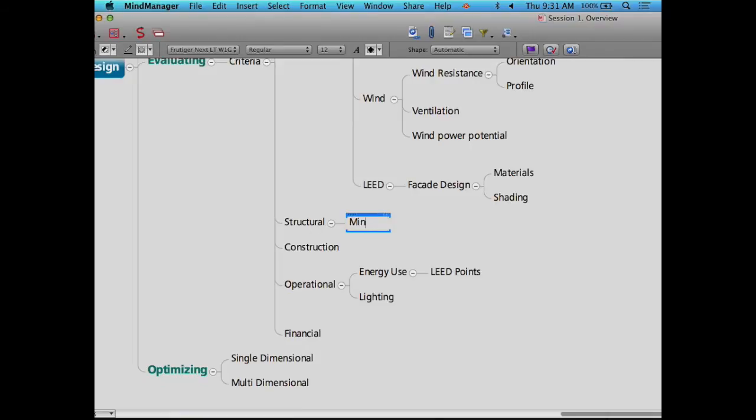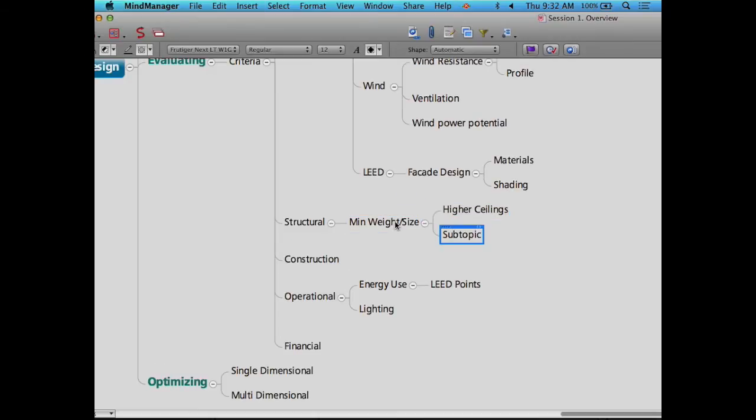Okay. And when you say size, is it size or is it weight? Or kind of both? Yeah, I guess it would be weight. Okay. Or it could be both, because you want to minimize the weight, but you also want thinner members, right? Mm-hmm. And why do we care about that? What's it really driving? Is it because we like less material, or less cost, or what is it that drives that? It allows you to have higher ceilings, and it allows more space for ducts. Got it. Okay. More space for coordination.